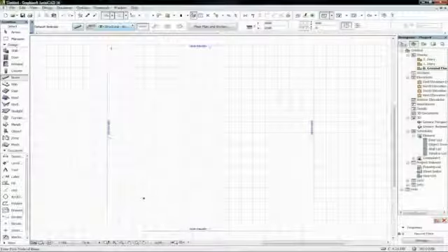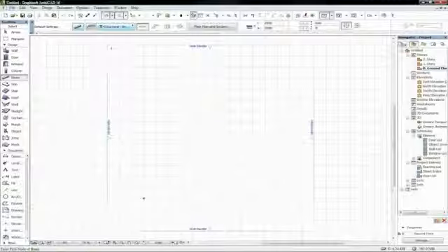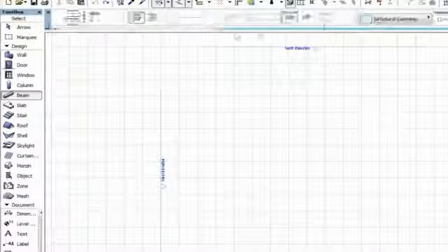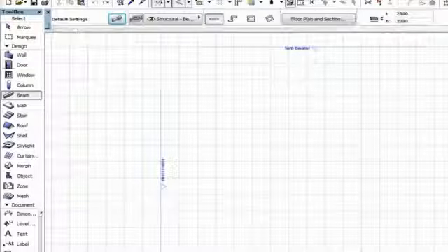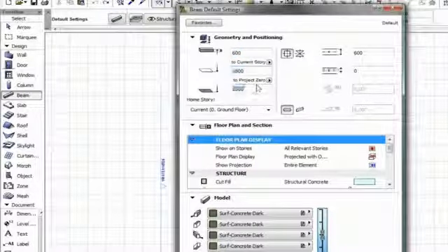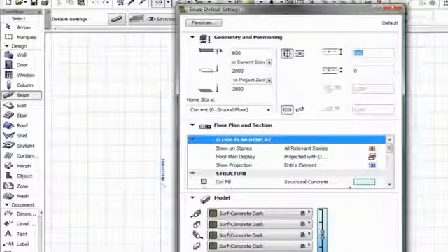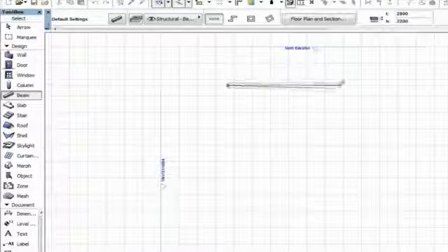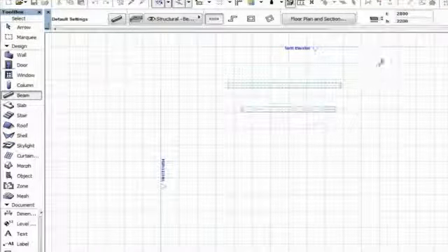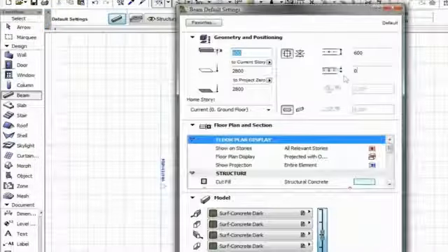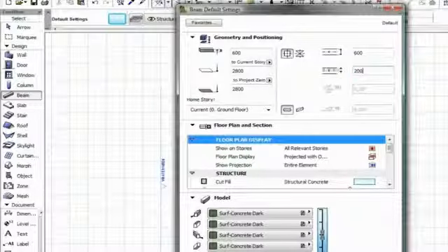All beam-related settings and parameters are available in the Beam Tool dialog. The most important ones are also displayed in the info box when the Beam Tool is active. To place a single beam, activate the Beam Tool from the toolbox, set the major dimensions and choose the single geometry method. You can place single straight beams with 2 clicks which define the 2 endpoints of the beam's axis line. The position of a beam can be set relative to the axis line, but with the default settings the axis line is always in the center of the beam section's bounding box.